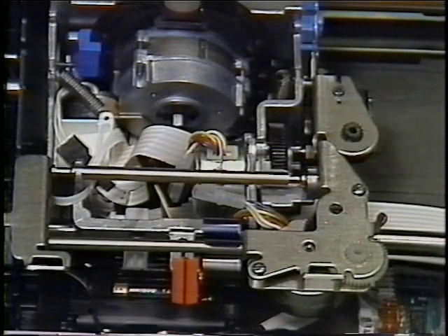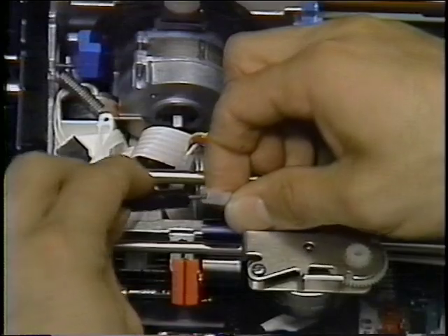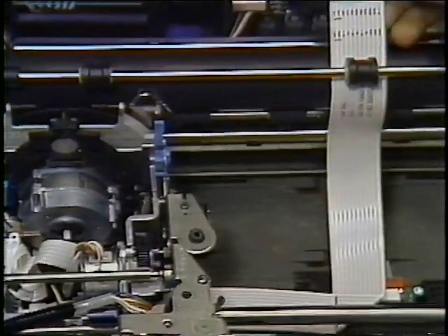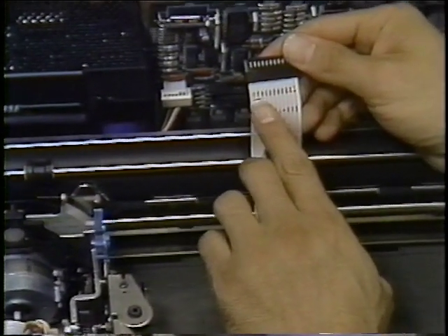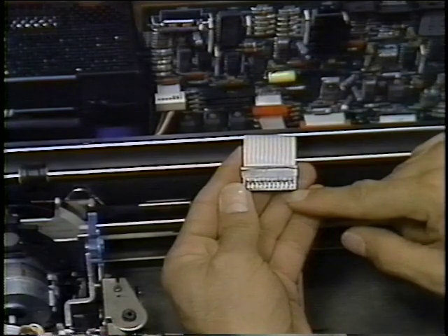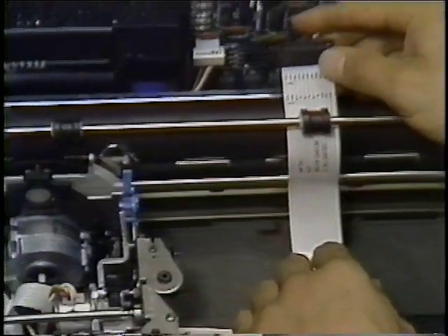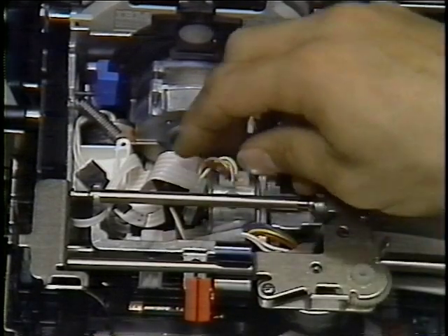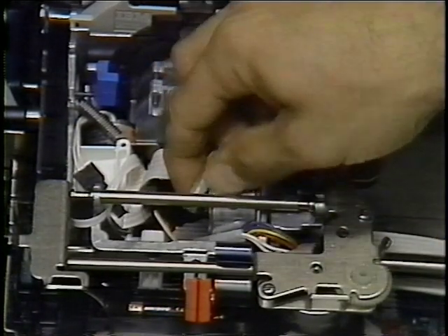In order to perform the ribbon feed motor resistance check, you will plug one of your meter leads in the test connector on the motor and measure the resistance from the test connector to each of the feed motor pins on the bottom side of the carrier cable connector. The resistance check on the ribbon lift motor is performed the same way as the ribbon feed motor resistance check.